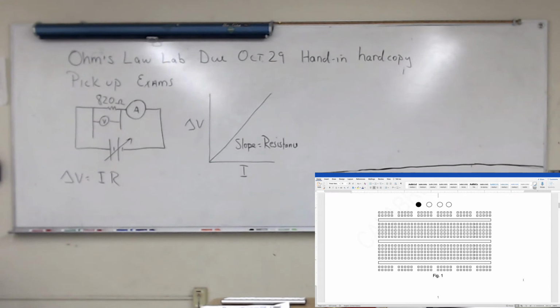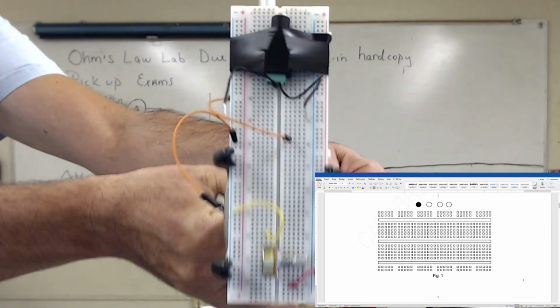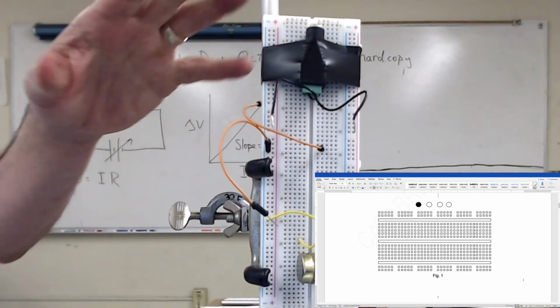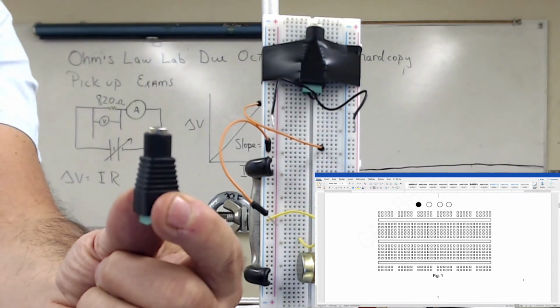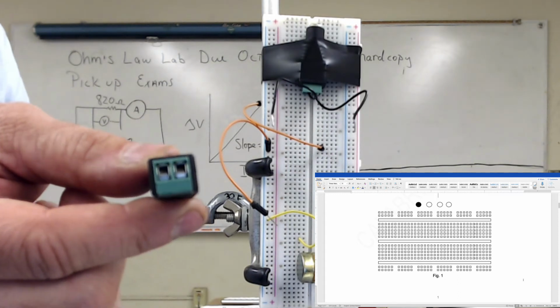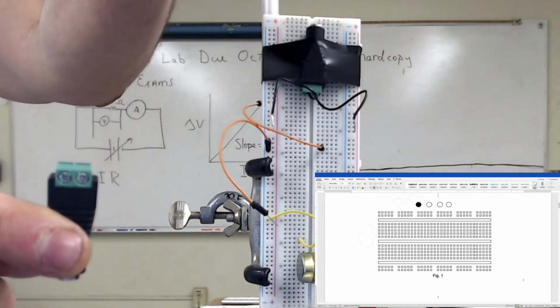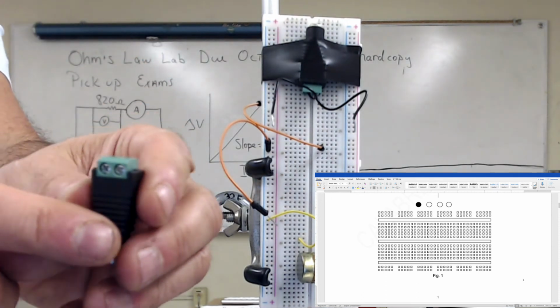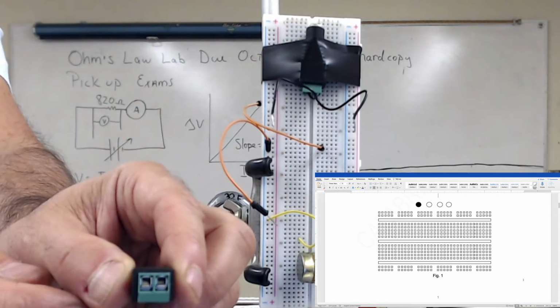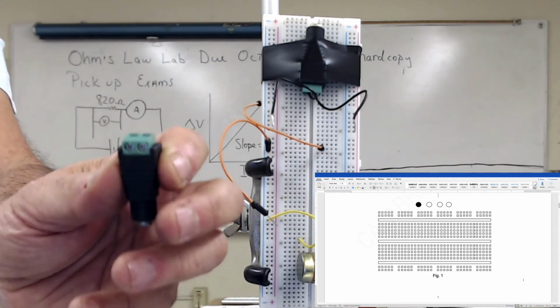So, in order for you to do the wiring, let me show you what I did. Now, granted, this is not the Protoboard you're using, but I actually taped part of it onto the Protoboard. So this comes with your kit. It has a green end. You can put some screws in and then use the screws to tighten them so that the wires stay in. You have wires in your kit. You put the wires on each one of these, one on each side, and then you use a screwdriver to tighten it so they stay in place, like these guys.